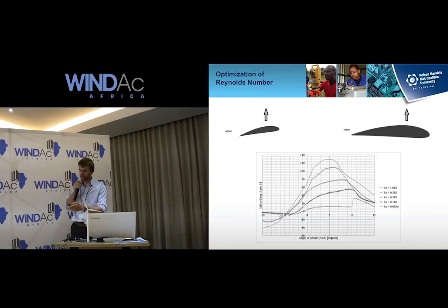So this is the crux of the way I've gone about it. That would be viewed as an optimized blade design there. And so I've increased the chord length, so made the blade fatter. But in order to have the same amount of force, I have to decrease the angle of attack. You can see that there's an angle to that blade there, and this blade is much flatter. So how is that? Well, let me just explain what would happen there.